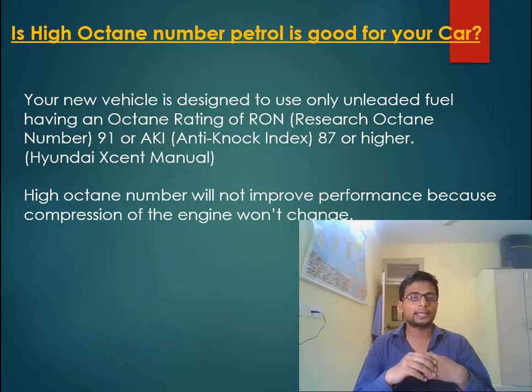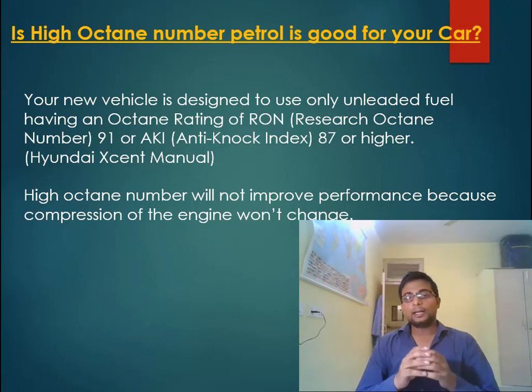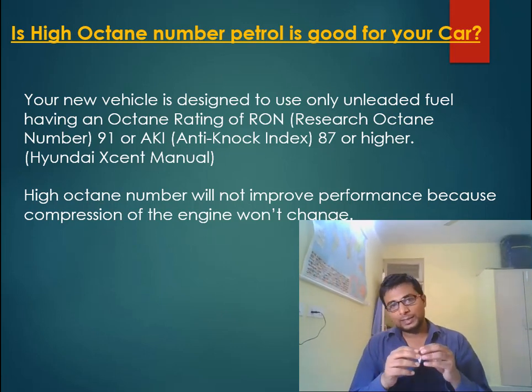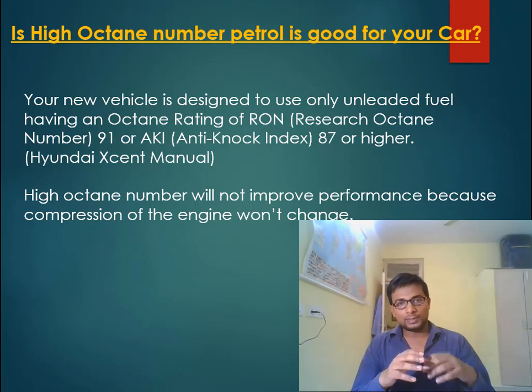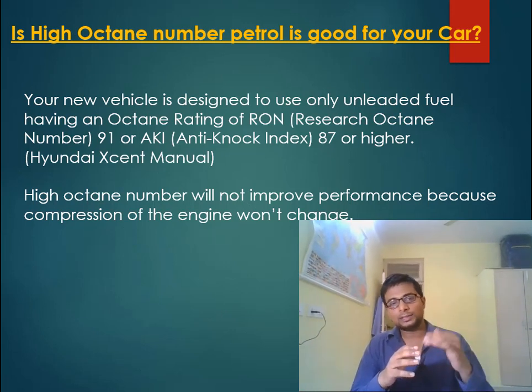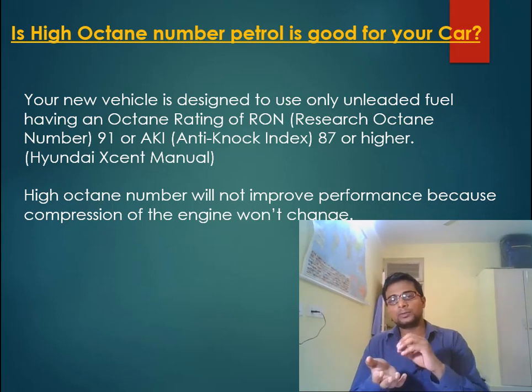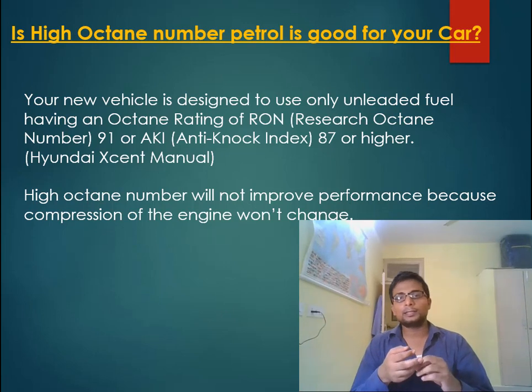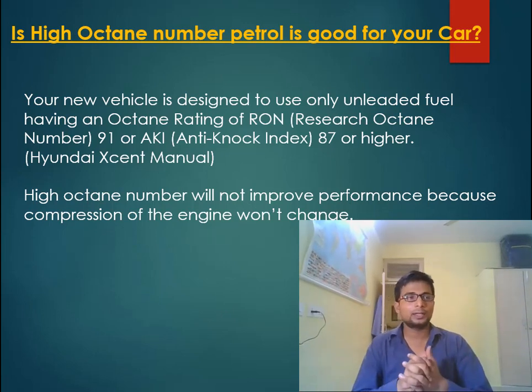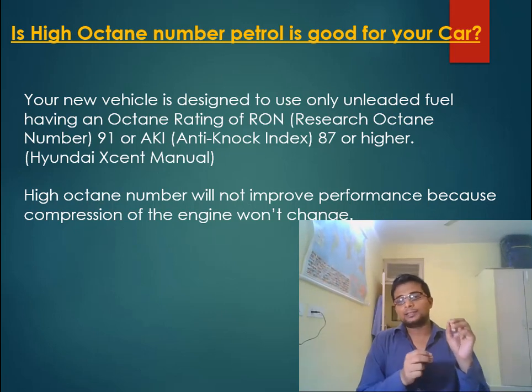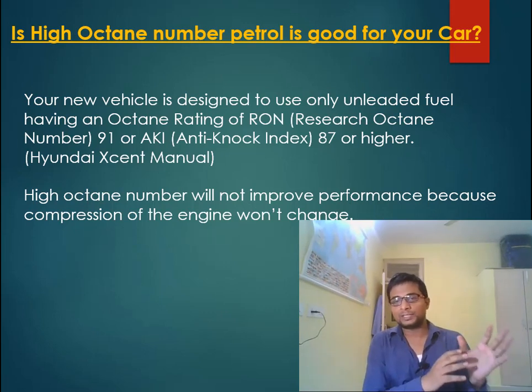so we should understand which type of petrol we should fill in our fuel tank. So if my car is designed with a compression ratio such that there won't be any knocking for octane number say 91 or higher, then in that car if you are using 95 octane number, it is wastage of money, because the car is designed for a given compression ratio.